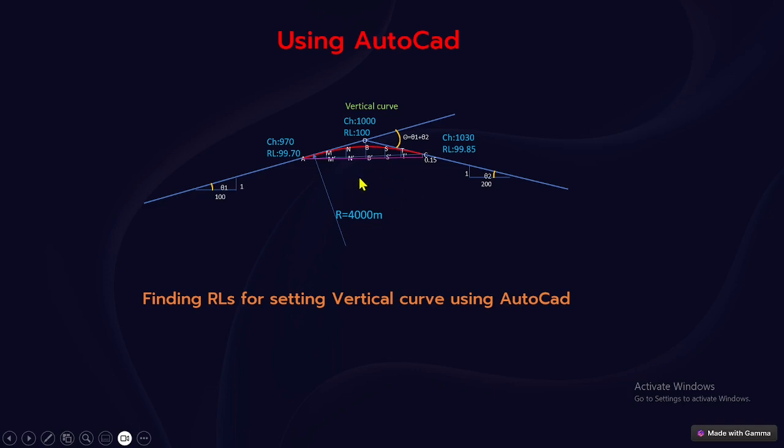Partly we do drawing and partly we do some calculation. This is one way, but a realistic way is also possible. Normally we'll have the AutoCAD profile drawing also. There, at the point where you want to introduce a vertical curve, straight away between the two lines you can introduce the curvature. Then there also you can straight away take the levels, select equal intervals, and get the coordinates, levels, x and y. That is also possible, and that will be the realistic way. Anyway, I will show both.